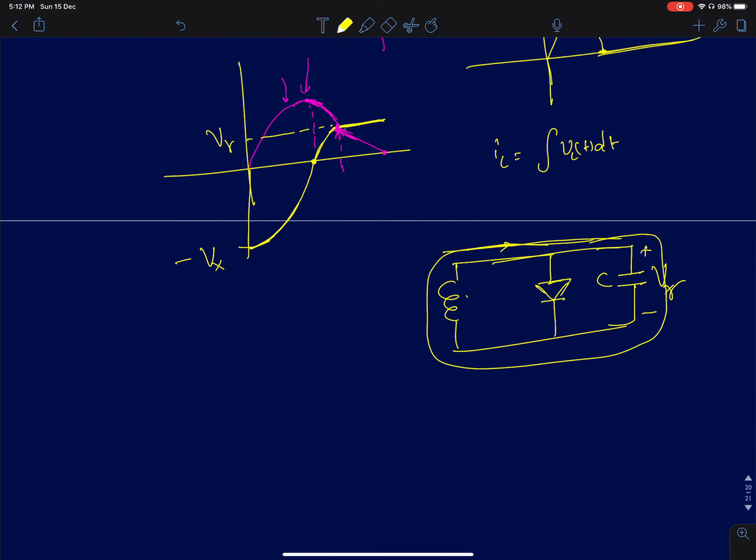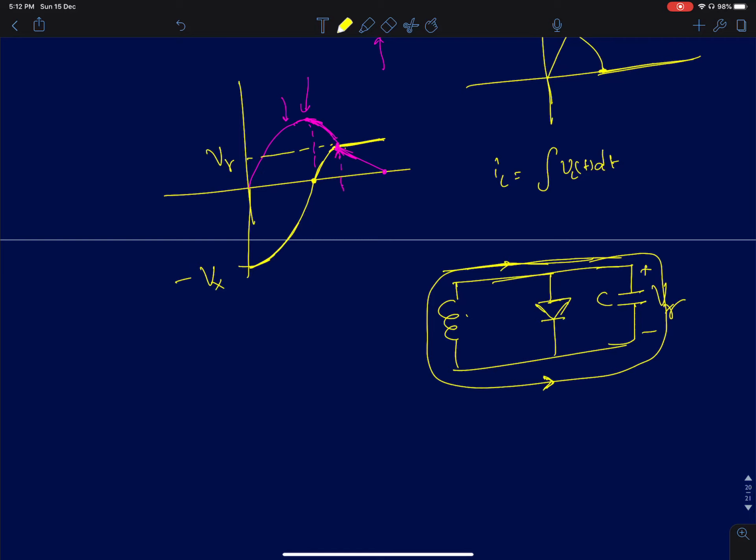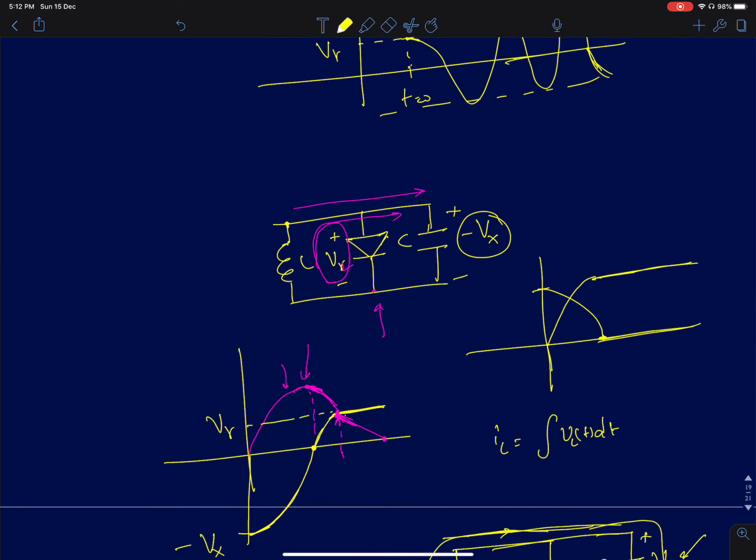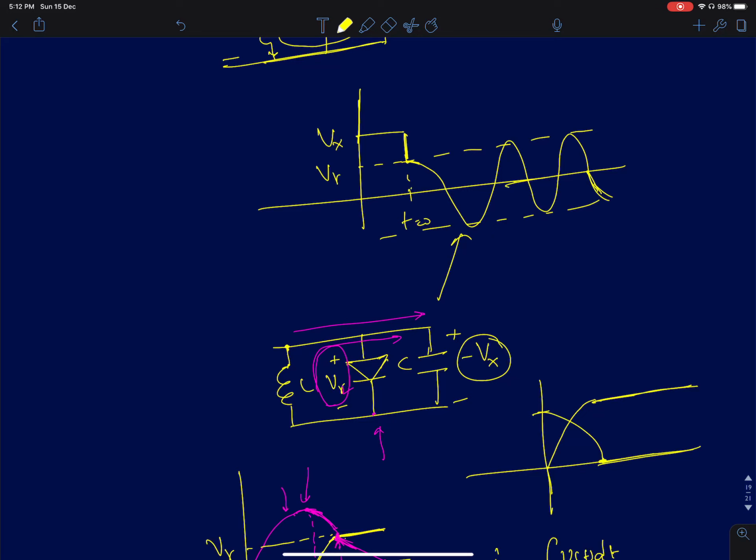Okay, the circuit would be like this. So now we have come back to the old circuit wherein we assumed a voltage. Let's say the capacitor was charged to a voltage slightly less than V gamma, then we said that it will just behave like a standard LC oscillator.